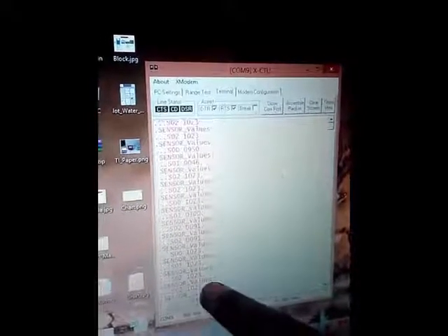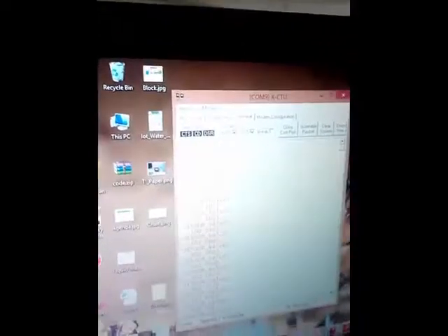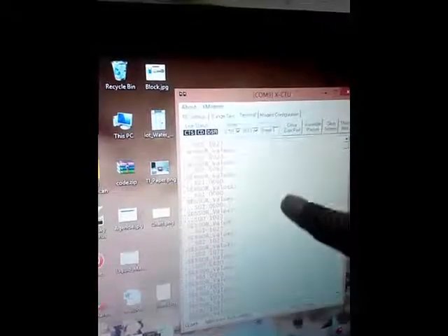If you see the sensor values, if their values are coming, then they will be varying. Now since no value is there, it is just showing the 5 volt, that is 1023. How I have coded it is that these are ADC values. The values shown are these ADC values. The 1023 belongs to 3.3 volts. As the voltage comes in, this value reduces. That's why in the previous XCTU terminal we saw some 500, 600 and so on.